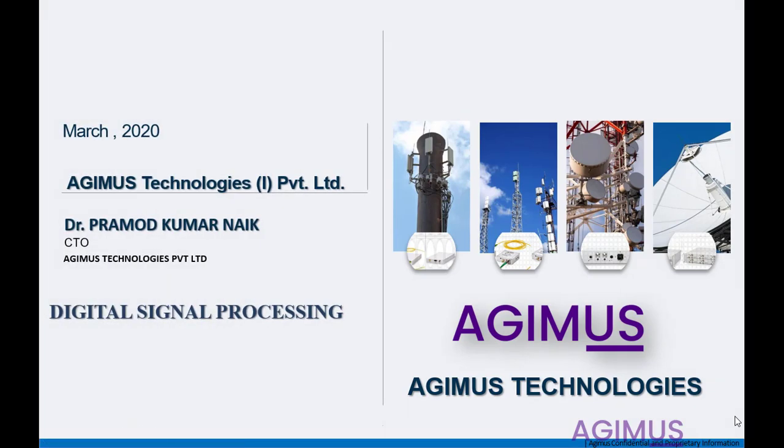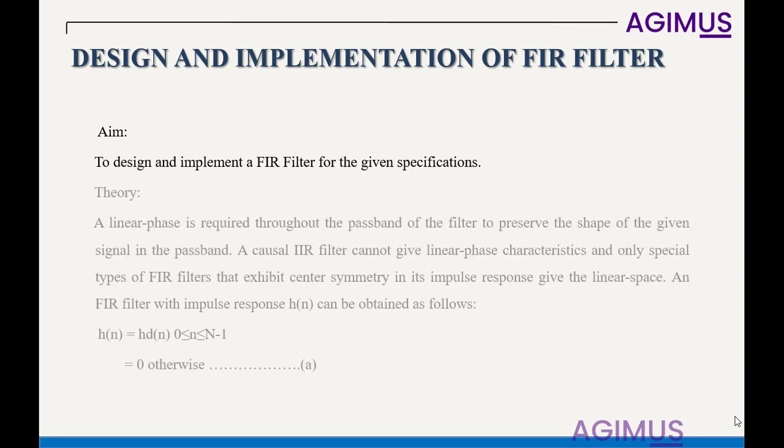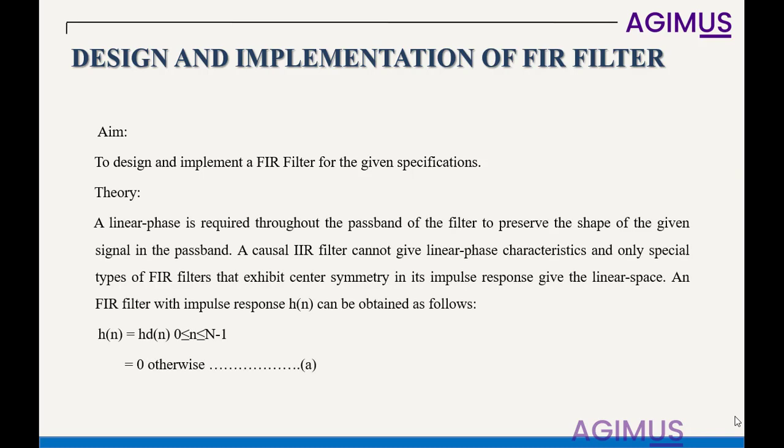Welcome back to this program on digital signal processing. In this section, our focus will be on the design and implementation of an FIR filter. To design and implement an FIR filter with the given specification, it is possible to use an inbuilt app in MATLAB called the FDA tool, the Filter Design and Analysis tool, where you can design the FIR filter in no time.